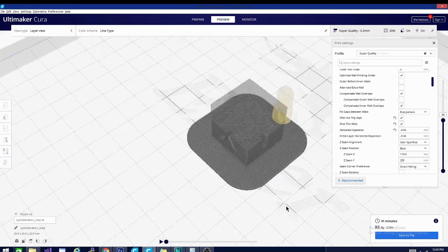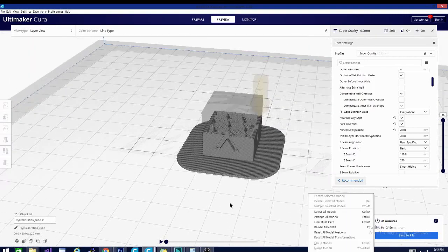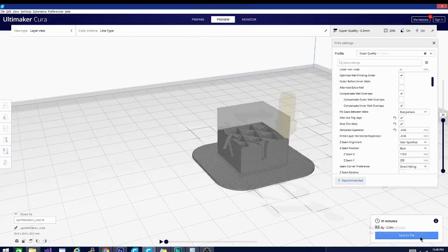That's going to be it about the seam. If you're getting weird line artifacts vertically through your model, or you're getting random blobs and zits all over through your model, it's probably the seam settings, and that's what I would look at first.